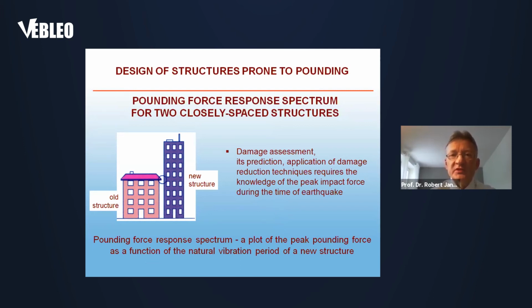The concept of response spectrum is not new in earthquake engineering. However, this idea is somewhat different compared to some previous analyses. The pounding force response spectrum can be defined as a plot of the peak pounding force as a function of the natural period of one of the structures.